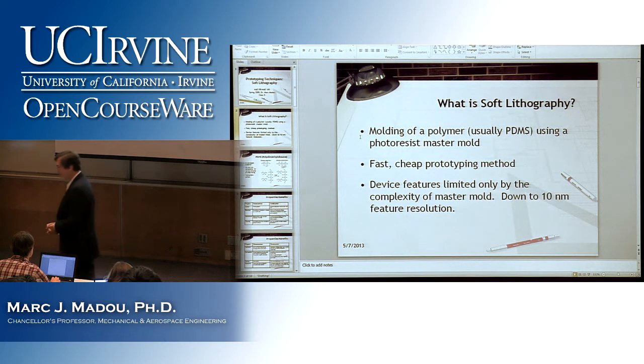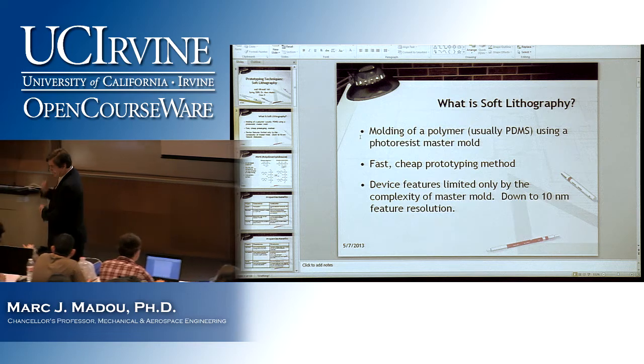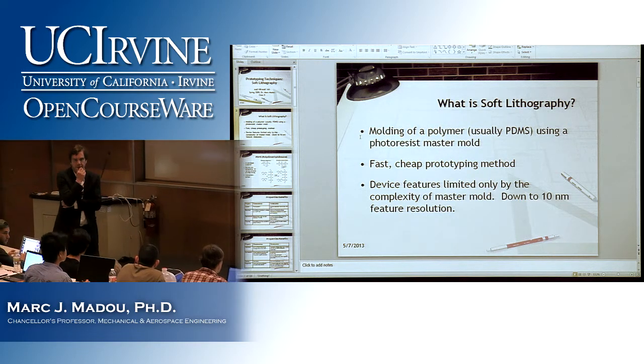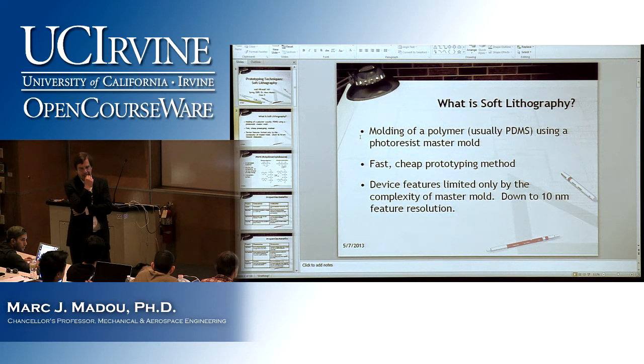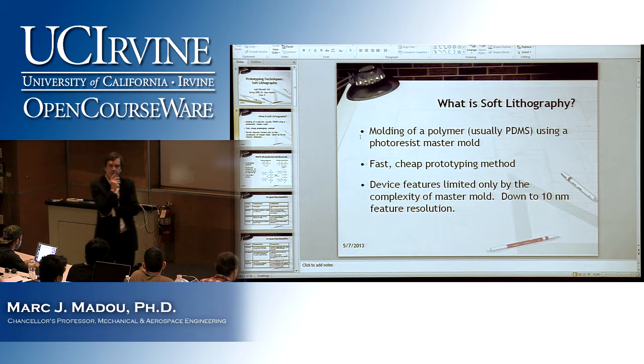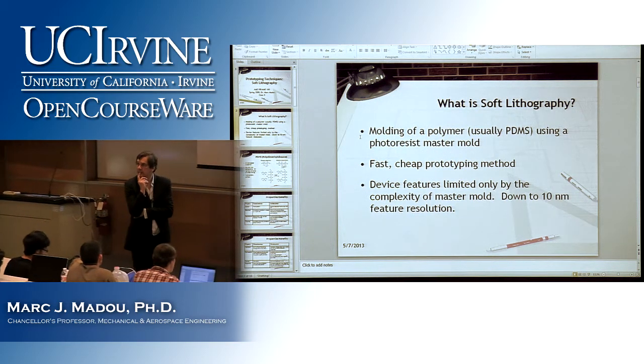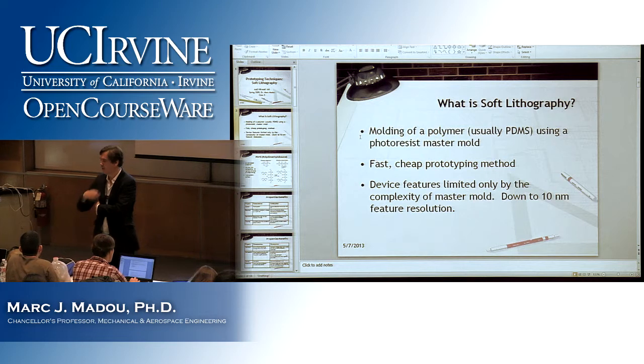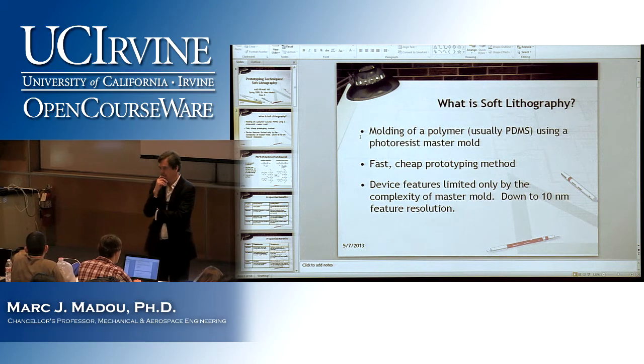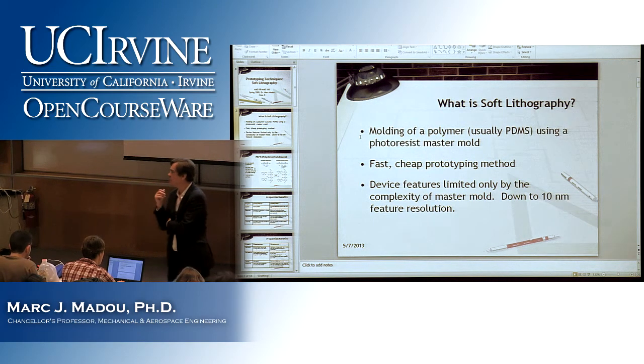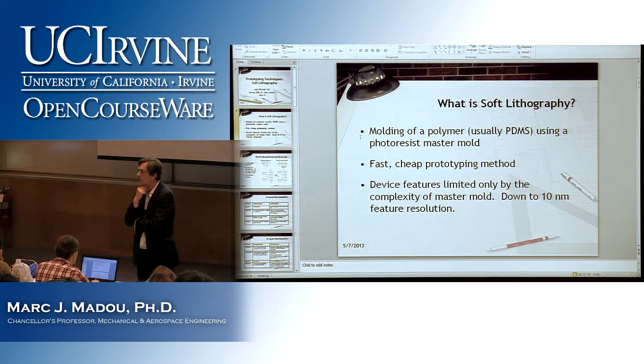I actually had a question about the angle of approach in whatever that was, sputtering. Right. Is it 65 degrees from the vertical or 65 degrees from the horizontal? From the horizontal. And by the way, that 65 degree is a very, very crude approximation, and it differs from material to material. Okay. So, yes, the 65 is kind of a crude random figure.